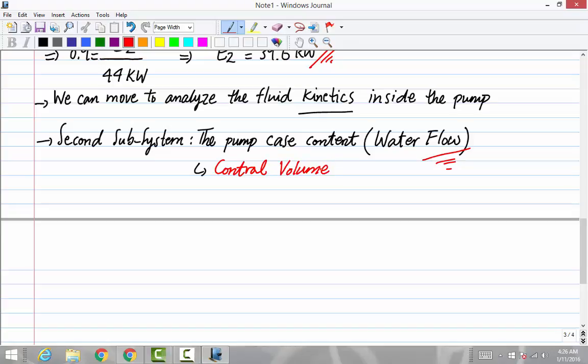Remember that I mentioned before, we have two different systems: control mass and control volume. Control mass is, as I told you, just a specific piece of mass, and we're going to stick with it and talk about those particular molecules. But in control volume, for example, it's like if you hold your hands around your eyes and don't move your head, just look in front of you, and imagine that these molecules are coming into the domain that you can watch, and they leave the domain, right? So you are talking about the boundary around your hands. That is the control volume that you are focused on.